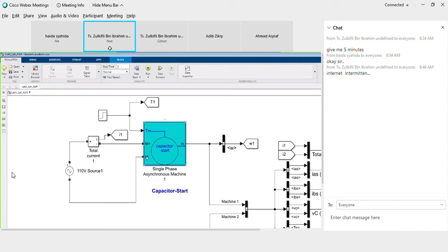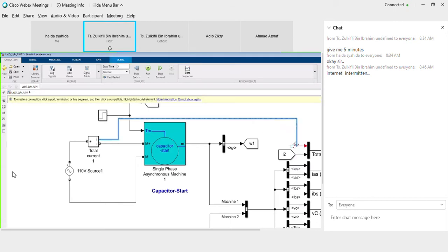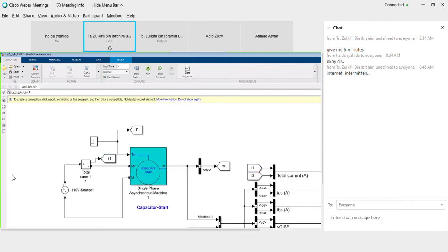And then this is just tagging, from here it will go to here. Why? Because we don't want to have clutter. You can do it like this, no problem, but it will look messy. It's possible, but it's messy. So we use what is available, meaning what can be used, as an improvement here. So we use tagging, meaning anything from here will go to here, and then click to the scope. The same goes to here.